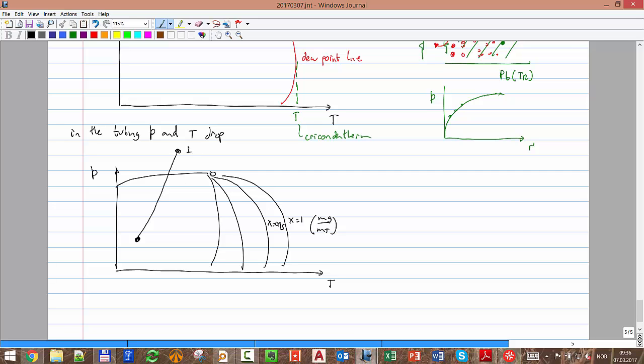So as I progress from the bottom hole all the way to the wellhead, I will experience a reduction in pressure and temperature, and that means that gas liberates from the oil. Or if I come from this point and I go inside, that means that oil liberates from the gas, or comes out of solution. It's a better way to put it.